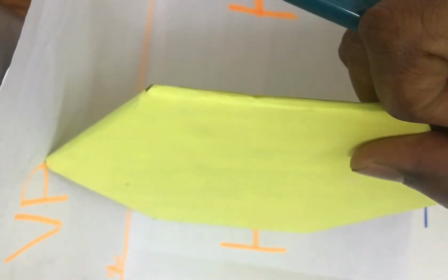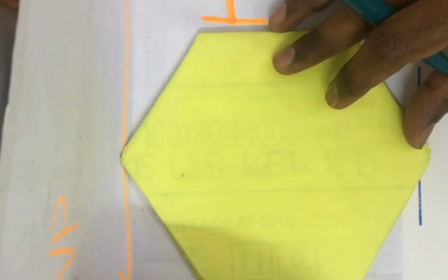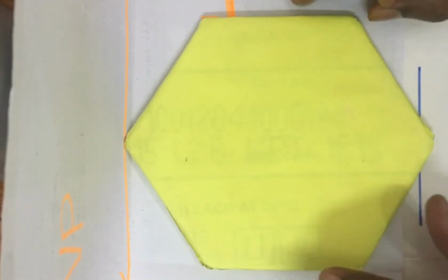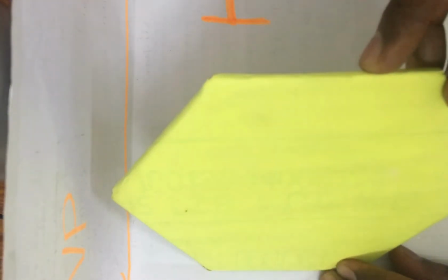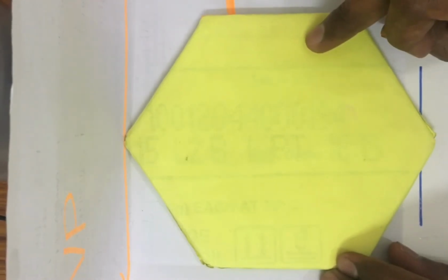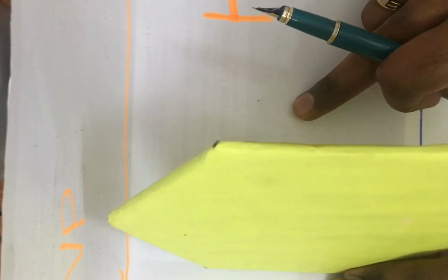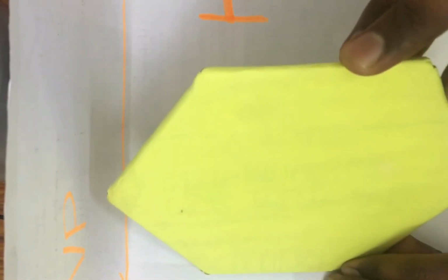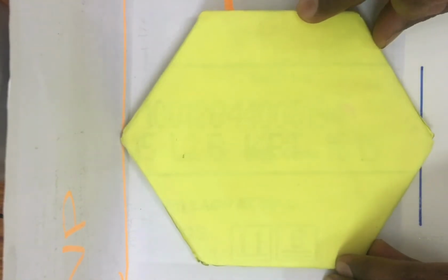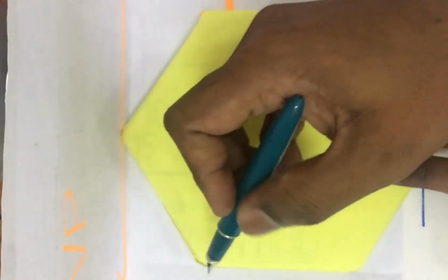When we view from here, we cannot see the true shape. So, we are supposed to place the surface parallel to HP. To which plane it is inclined, to that plane we are supposed to place it parallel. As the given question says the surface is inclined to HP, what are we supposed to do, dear students? To get a true shape, we are supposed to place it parallel to HP. So, this is the condition. I can give you the question once again.